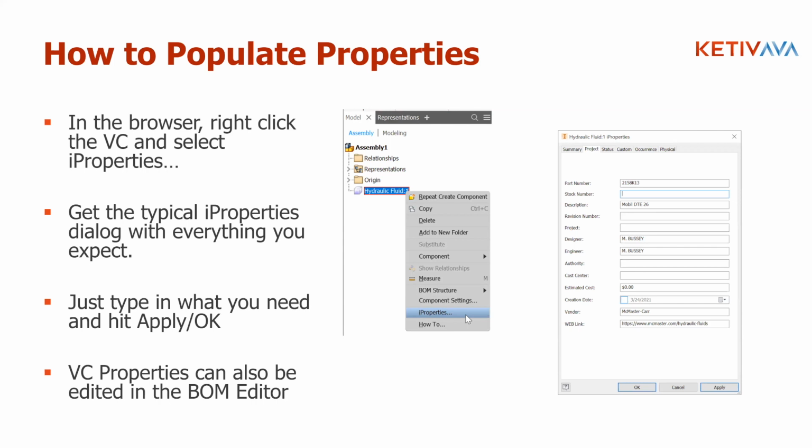Like, you really don't want to be manipulating the parts list because that data isn't stored. Like, if you delete it for whatever reason, you need to repopulate it, all of that goes away. Most of all your manipulation needs to be happening from the bill of material level, which is exactly why you would want to use virtual components.